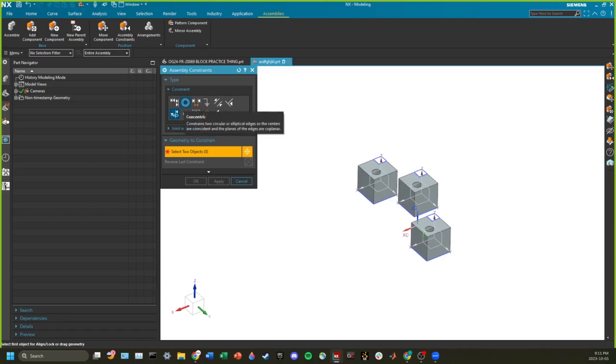Concentric. I have 2 rectangular parts, but with 2 circles, and I say join them together. If I put a bolt through this, that hole is the same all the way through, despite it being 2 parts. I have the ability to rotate. I don't have the ability to leave the face. It connects the 2 faces.